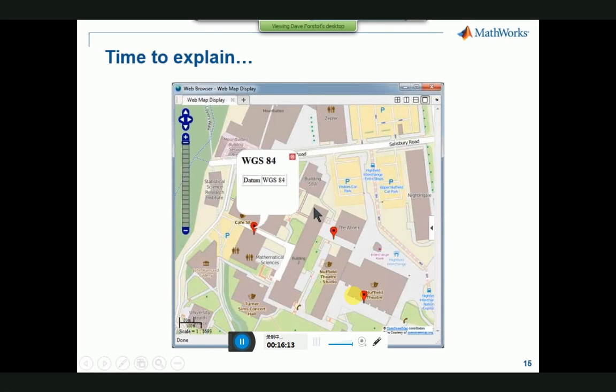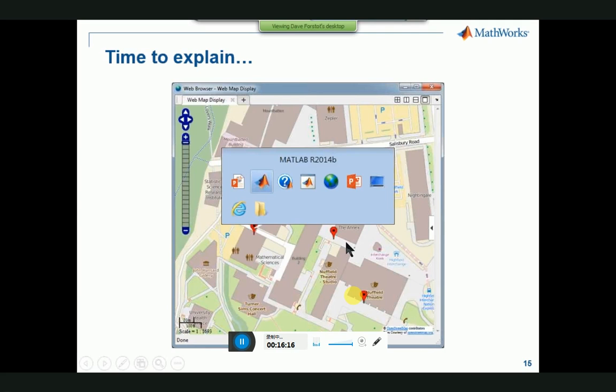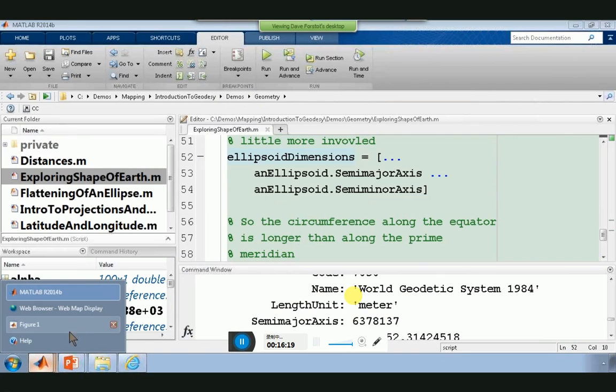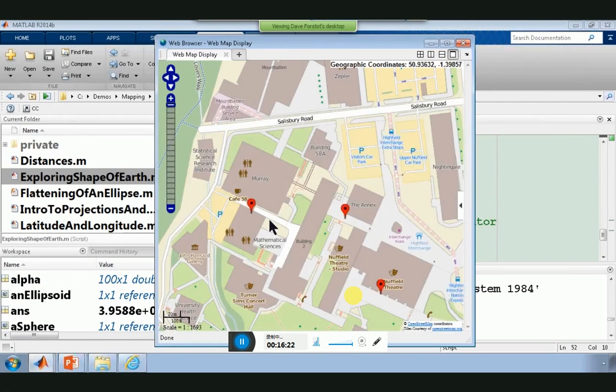So if we go back to that initial visualization, let me bring that back up. What we had was 3 different positions using 3 different datum. Today, if you looked at a GPS or your smartphone, it would likely report to you your position using something like WGS 84, the World Geodetic Survey of 1984. However, I mentioned those 2 other datum, the datum that was defined to specify position in Great Britain, as well as a European datum.